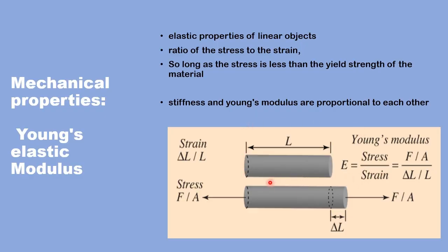All objects or structures have an inherent mechanical property that is intrinsic in the material of the object or the structure. It's the way it resists deformation, like stretching or compression, when a force is applied to it. Stress is defined as the force applied to the object to cause its deformation, either stretching or compression, divided by the surface area of the object or the structure perpendicular to the direction of the applied force.